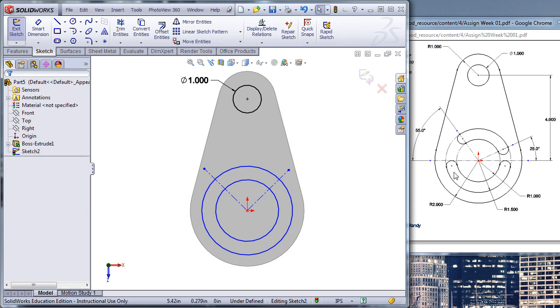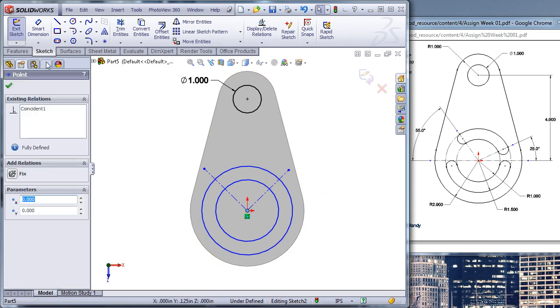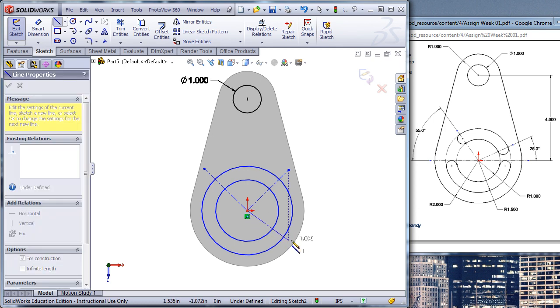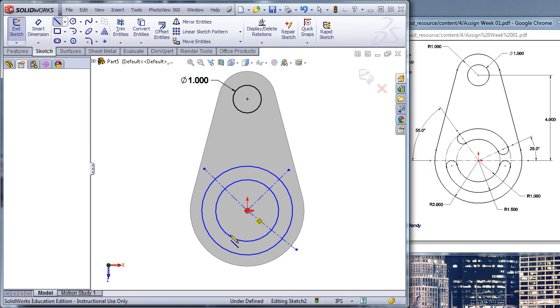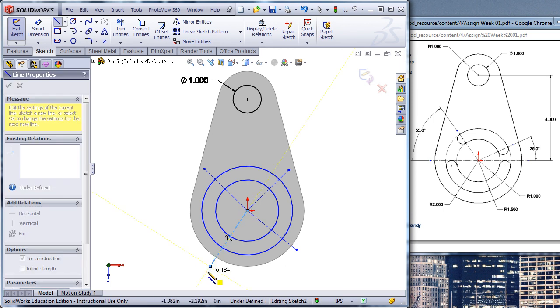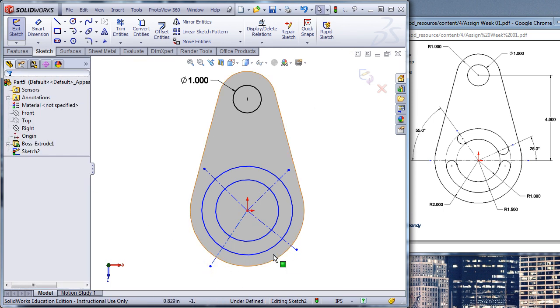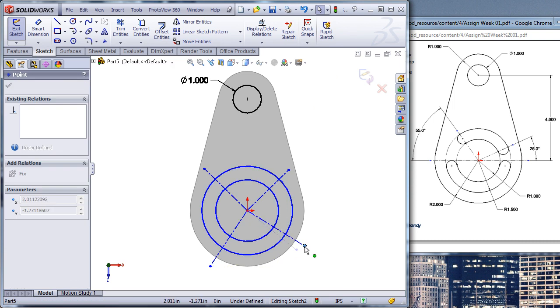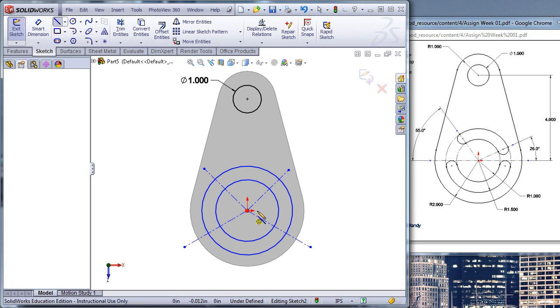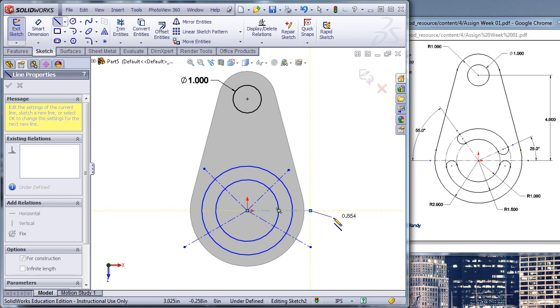And then, even though you don't see them, I'm going to create a construction line, center line. Those two terms are interchangeable. You'll see them used in SolidWorks literature, both terms, down like that. And it really doesn't matter where they are. I want to make sure I didn't create a relation here on that one. It doesn't look like I did, so we're good. Finally, I need one more center line, construction line. I'm going to put one in right here.